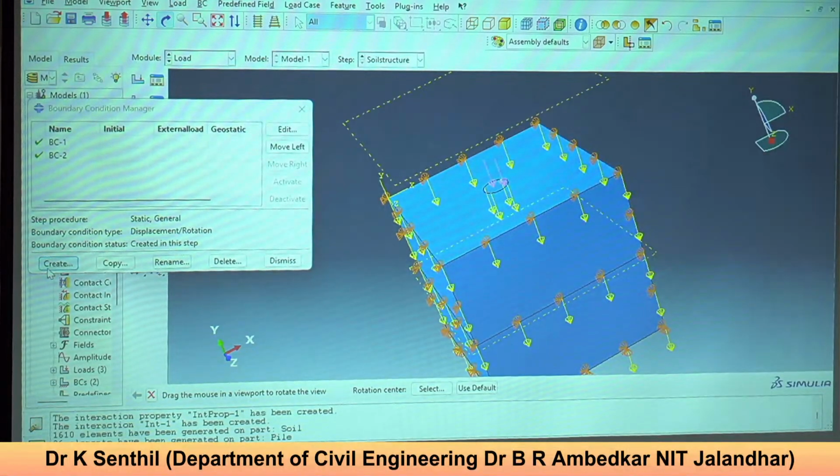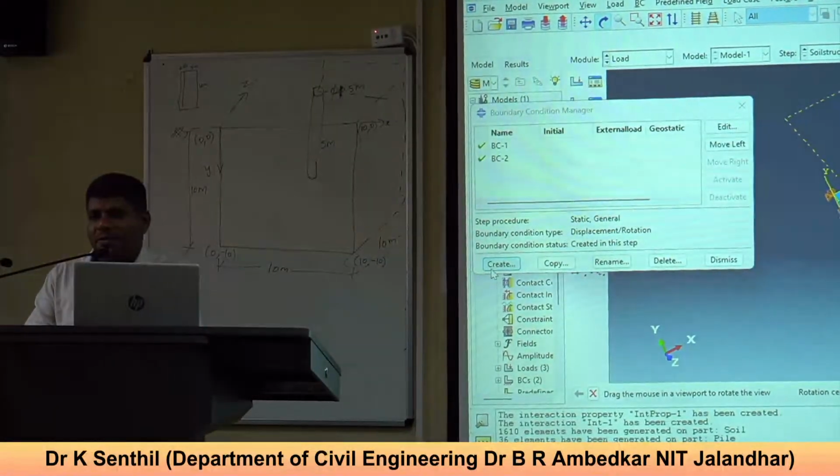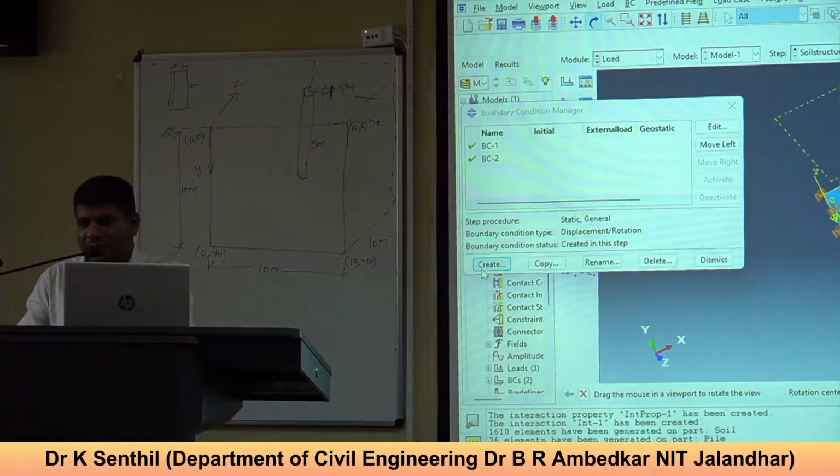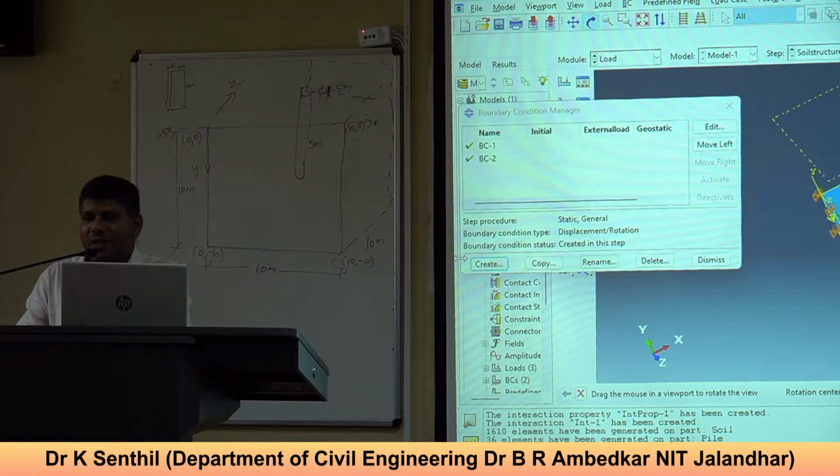Because in FE, you can do force without mass. When you shake the whole sample, the whole domain, it's going to come as horizontal motion, so you need mass on the top. You need to create a point mass and make it deflect, some settlement, so you get the inertial effect as well.